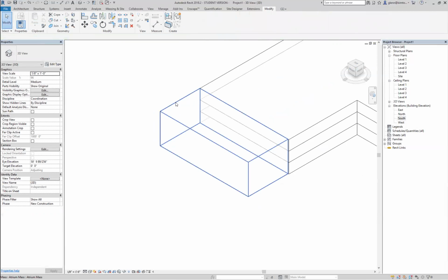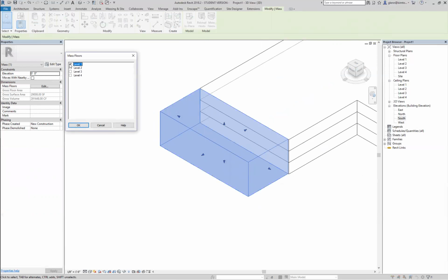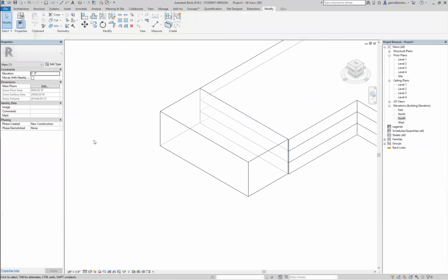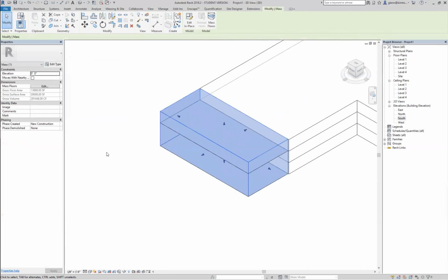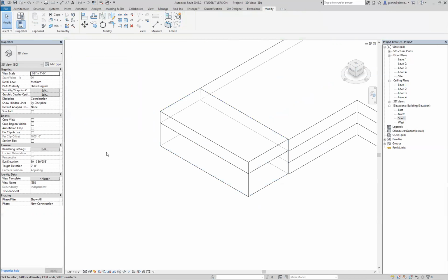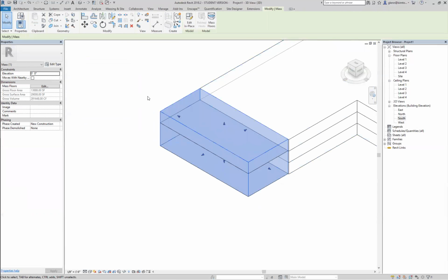The reason for creating the 2 different masses is this now gives me the ability to have different mass floors. So if I want a first floor, but I don't want a second or third floor, I could have that. Or if I want a first floor and a third floor, but without the second one, I can do something like that. So you can aggregate things together in different ways. So I have mass over here. I have some mass floors over here. Because I've now created 2 different masses, though, I can't just select a single one of these boxes and figure out the total amount.